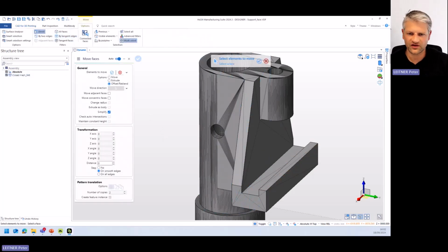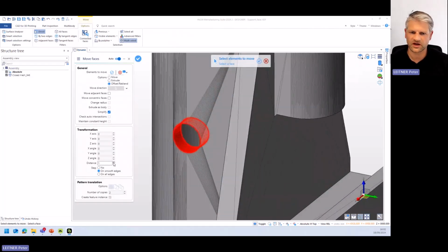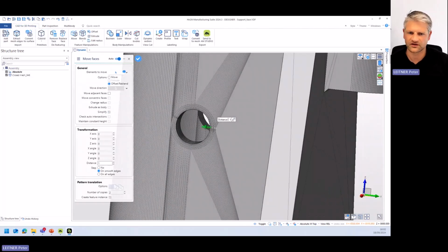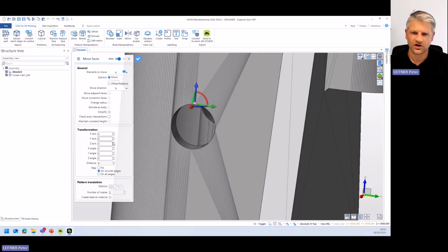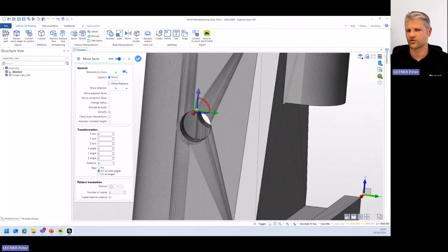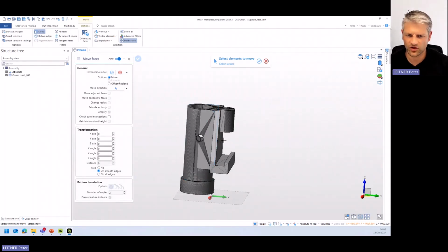And what I wanted to showcase here is, I can now take this hole here, and I can, for example, make an offset onto that. As you can see, it's now remeshed and it's offset to the inner 1 millimeter, or from, for example, 2 millimeter to the inner. Or what I can also do is move the whole thing in X, Y, Z direction. So for example, I want to move it 1 millimeter to the left and 1 millimeter in Z for whatever reason. So you can, again, very efficiently, from my point of view, work with the mesh as you have worked with the CAD surfaces.